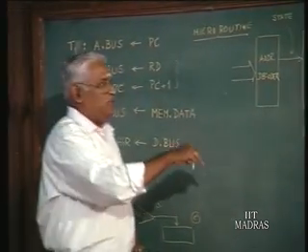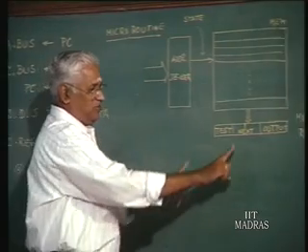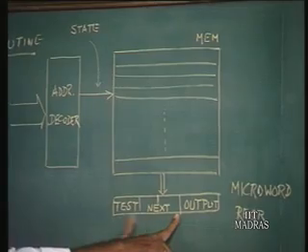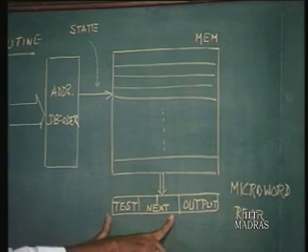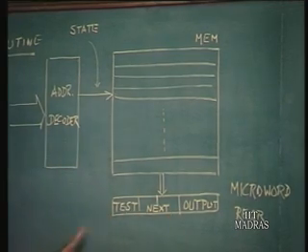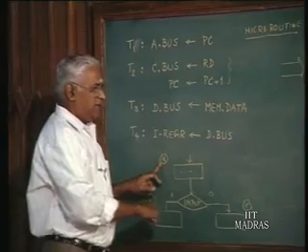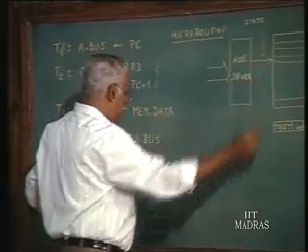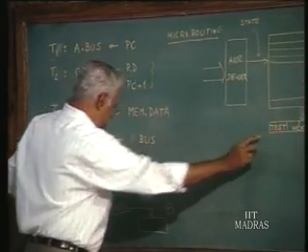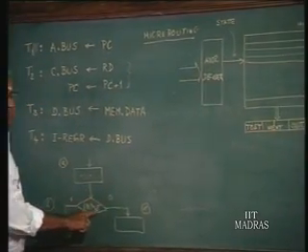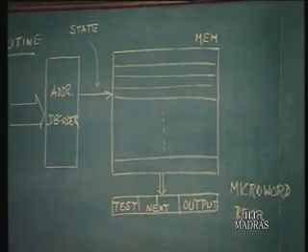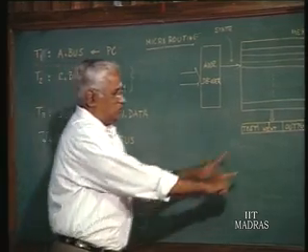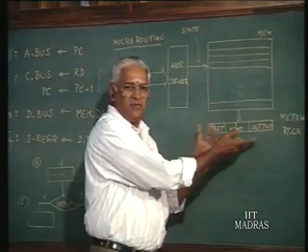Then what about the sequencing? That sequencing information is available here. This part is only for the data path setting; here you have the sequencing. It says, okay, is it state A? Fine. If this is state A, this word will say test for some input. That information will be available here. Then it would also give these 2, true or false next states.